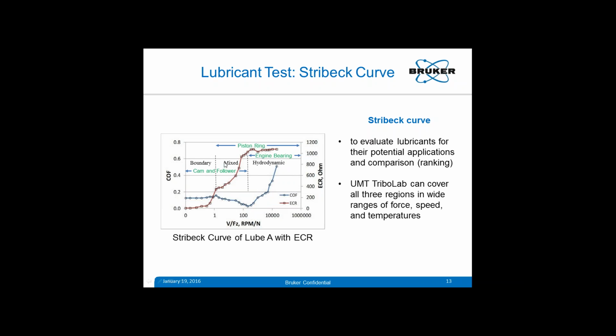Now you see the automotive components, like the piston ring, it actually operates from mixed to hydrodynamic regions depending upon which portion of contact it is, whether it is at top dead center or in the center and things like that. Engine bearings are mostly in hydrodynamic conditions, where you have a lubricant film. And cam and follower normally operate in the boundary and mixed regions.